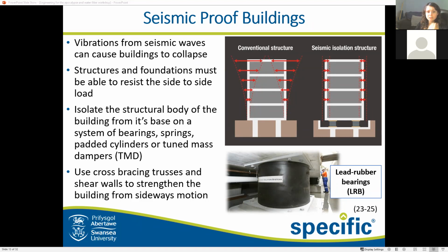And these bearings are attached to the building at the foundations using steel plates, so that the foundations can move freely without affecting the building. However, for this to be effective, you need stiff ground with deep foundations and driven piles. Otherwise, it can still vibrate, but this can be incredibly effective, and there are multiple methods available for this.